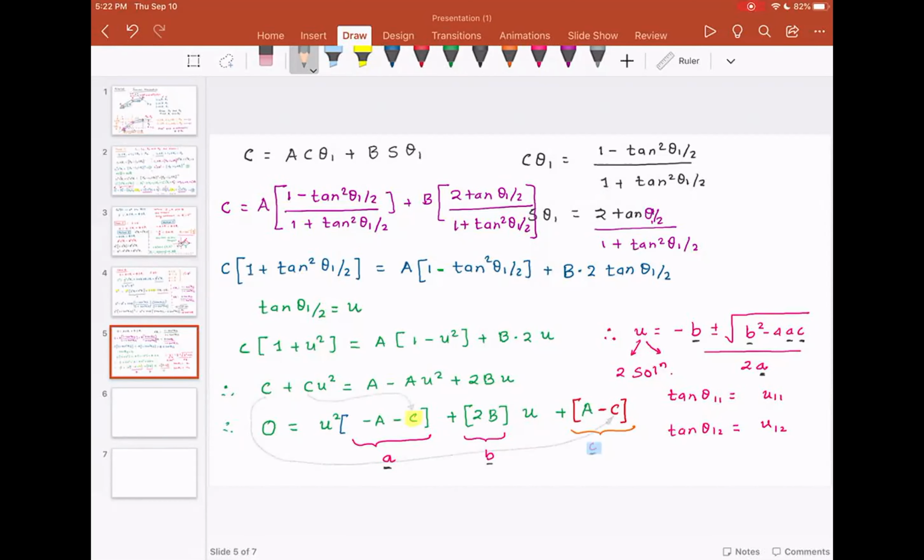Okay, so some of you may think, hey, this is too much mathematical jugglery, but believe it, we have to go through all this to find the solution to the inverse kinematics problem. And sometimes if you are using MATLAB, you may be able to solve transcendental equations with sines and cosines with numerical techniques.